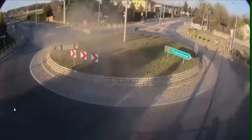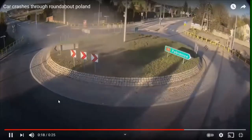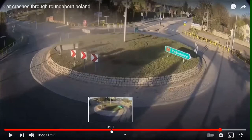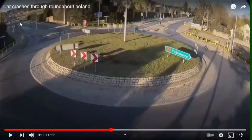What is this? This is a car crash in a roundabout in Poland. They just took off. So what was the reason for this? Look carefully at the splitter island. The splitter island doesn't have the geometry to force the driver to slow down. You see my point?